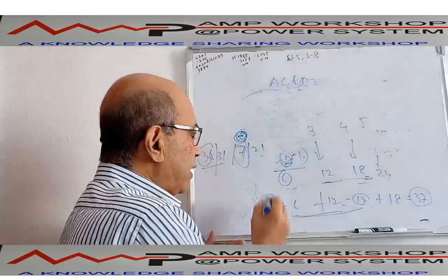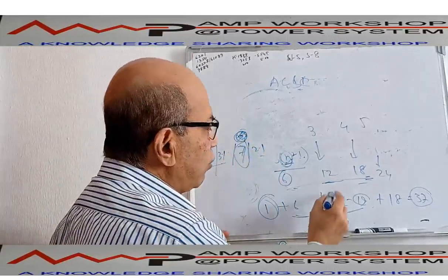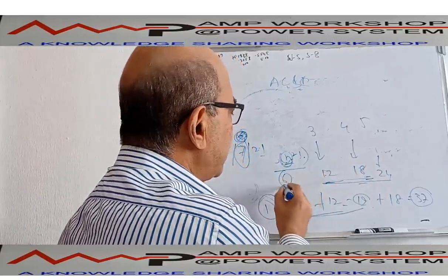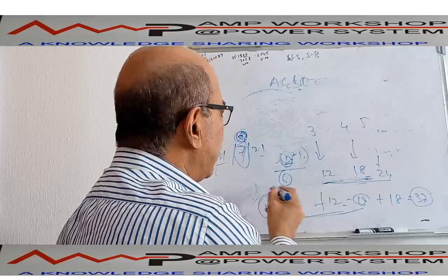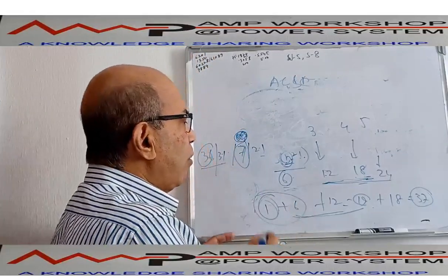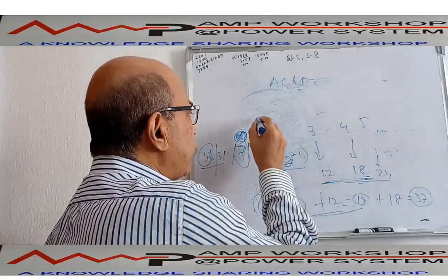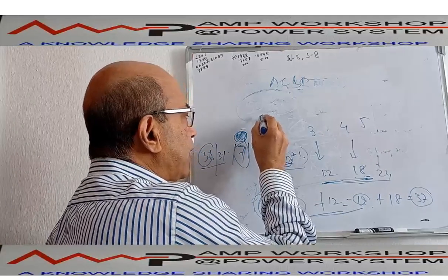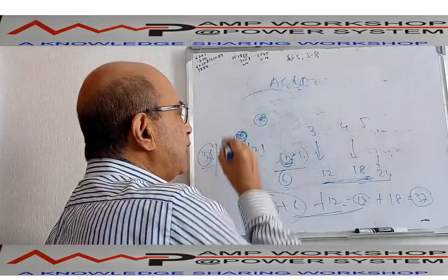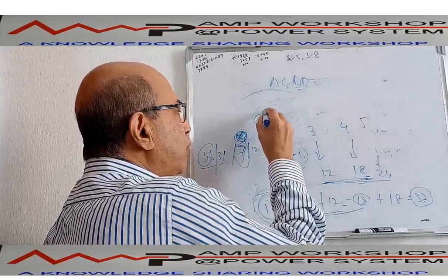The 7 number strand is the center strand, and outside we have 18, 12 and 6 strands. Okay, 6, 12, 18 in this way, 3 layers. So the center layer is one conductor, but that one conductor is again made like this. Or sometimes it may happen that instead we make 2 layers. One layer is the center conductor of steel, then another 6 conductors are also steel. This part is the reinforcement.